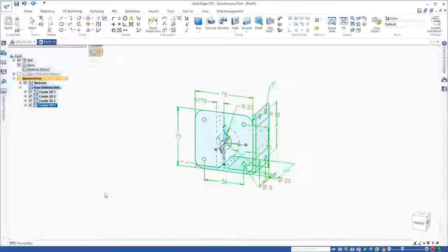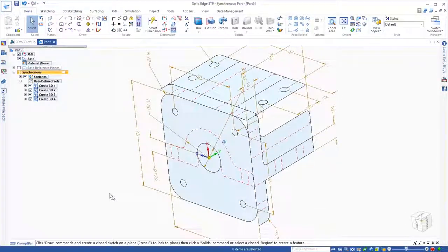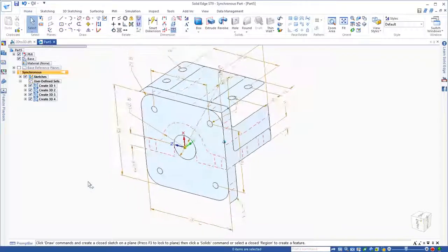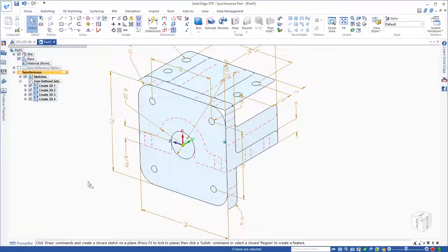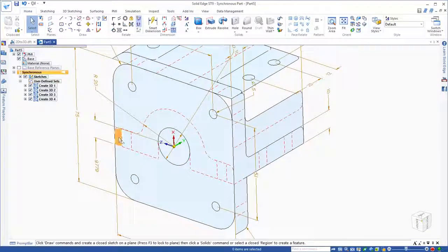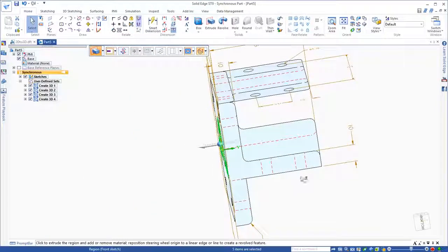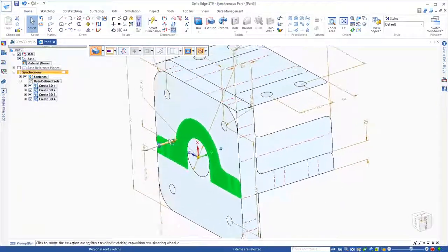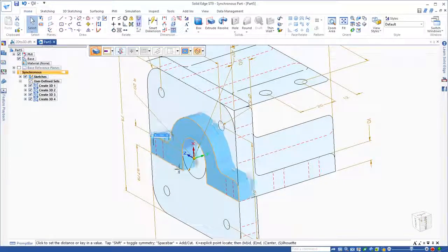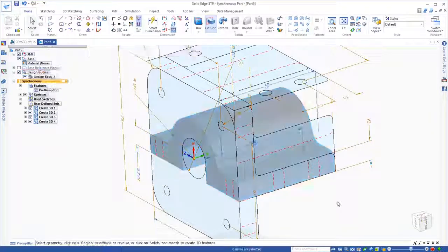And what that does is it aligns those views in the 3D space. So then we can take advantage of that geometry that's already been created, the manufacturing information from the DWG file, and begin to create a 3D model. So I'm just going to select the regions created by the intersecting sketches. First of all, for this particular shape, I can see that it's extruded all the way to the right based on the 2D drawing that has that view that's been aligned.